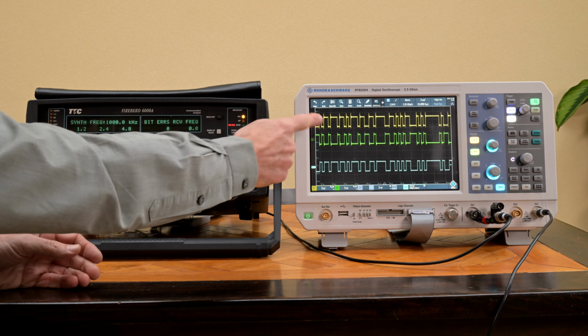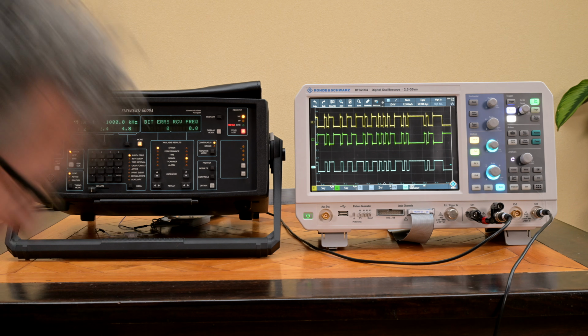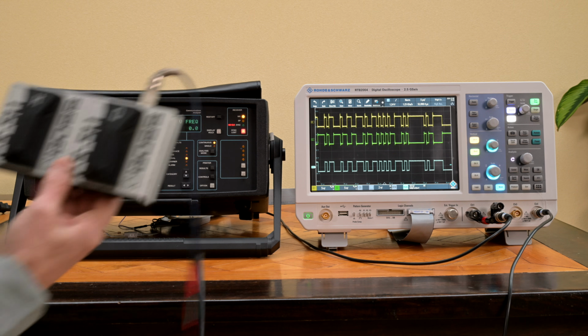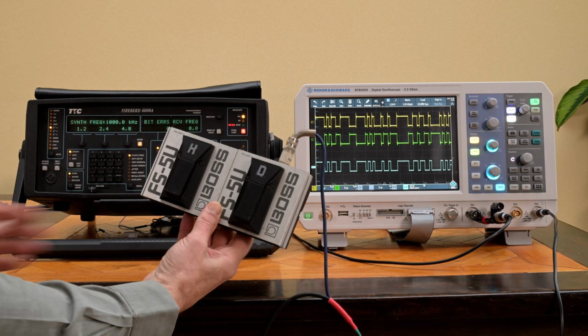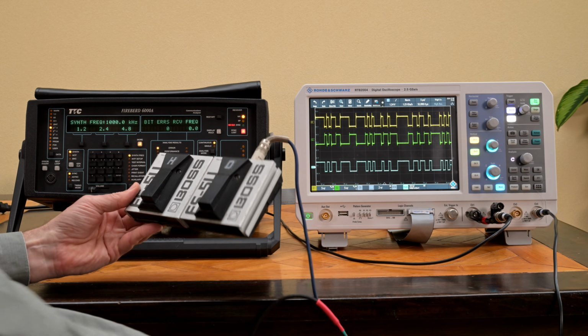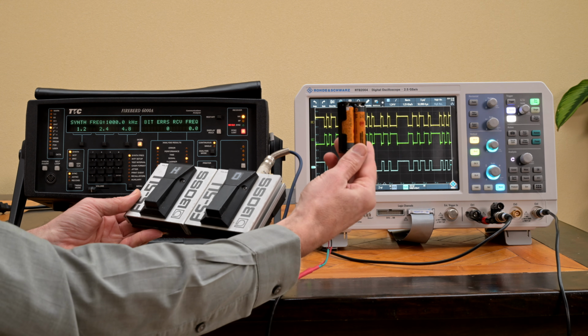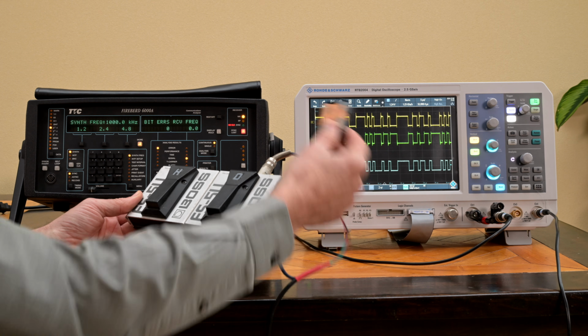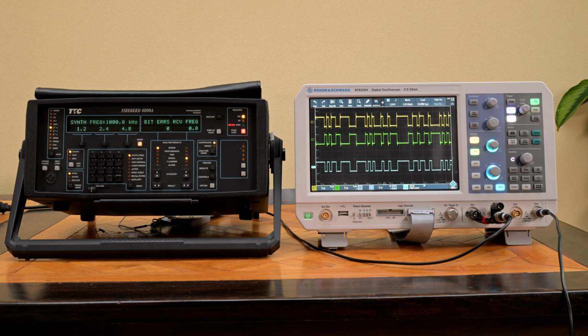In case you're wondering where the magical trigger from the scope comes from, well, that's very easy. I'm using a couple of foot pedals to do that, the ones that you regularly find also in the music field, and I'm just adding a couple of old, usually depleted batteries in series with it, and use it as a sync input for my scope, which is an easy way to trigger signals when I have my hands already occupied. So that's a nice touch on the LAB interface.